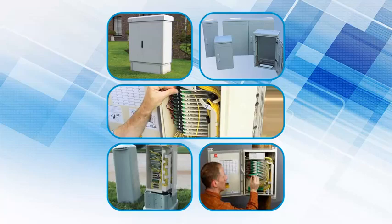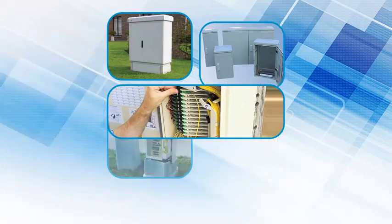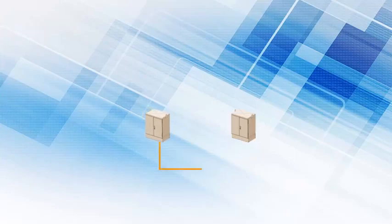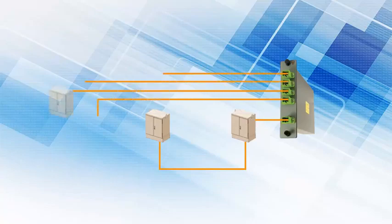FDH cabinets are often used to store PON splitters, which also require flexible connectivity to subscriber-dedicated fibers. An important factor in the rollout of new networks is speed. Cabinets can be provided direct from the factory, pre-stubbed, tested, and terminated. The cable stub is run back to the next closure, offering a patch panel for simple plug-and-play connectivity, allowing faster installation and reduces the incidence of installation faults. This style of cabinet can be combined with plug-and-play PON splitters, which can be installed as and when required, without the need for further field splicing.